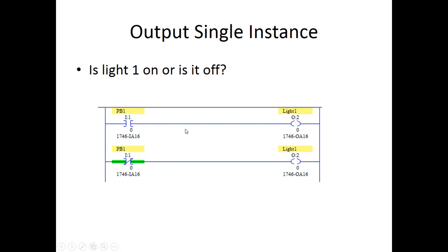And just think about if I did push the push button. If I push the push button, then this would close and this would open, which would turn the light on, but this rung seems to say that I should turn the light off. So you're going to get confused there about whether the light's on or off. In this case, it's going to take the very last rung here and solve that, and then that is going to be what gets pushed to the output module.